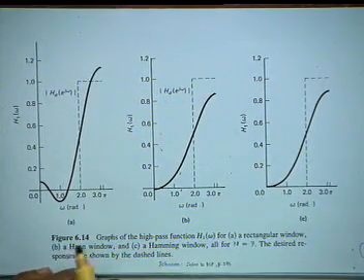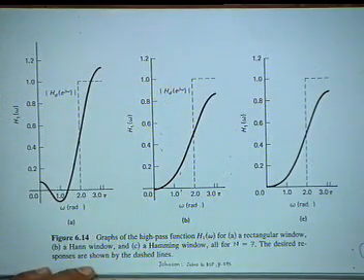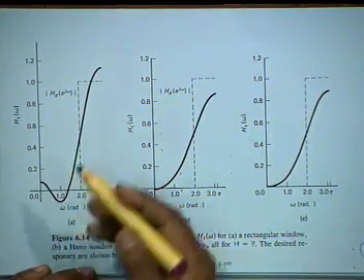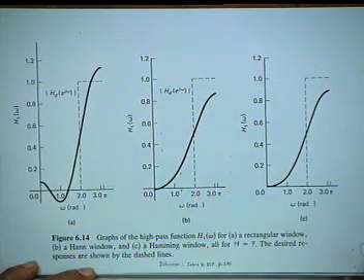So the comparison must be in terms of what tolerances have been put on your design. The pass band tolerance, in all probability rectangular window will not work, therefore you have to use either Hamming or Hann window.